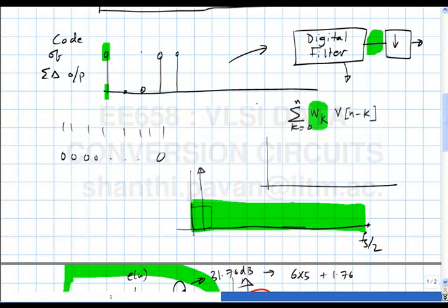So see, please note that the spectrum coming out of the sigma delta ADC is something like this, alright. And what I am doing in principle is cutting off stuff like this, correct? And if you want to realize a magnitude response like this using an FIR filter, you can use all the techniques that you learned in DSP to find the coefficients of the FIR which will give you this kind of magnitude response, okay.